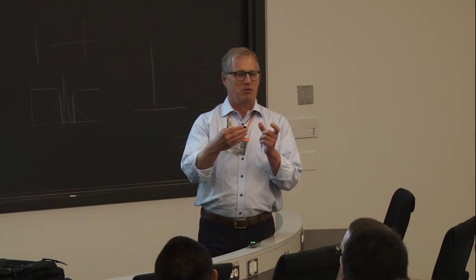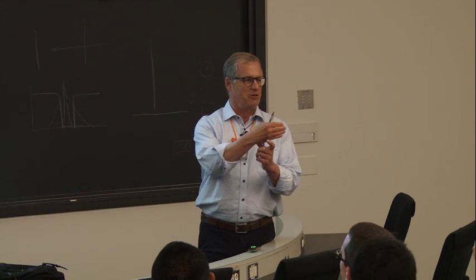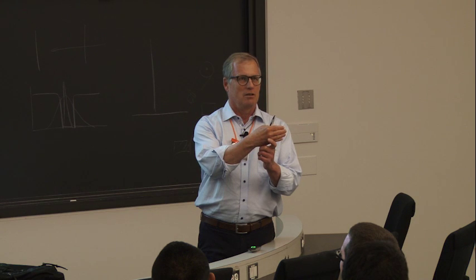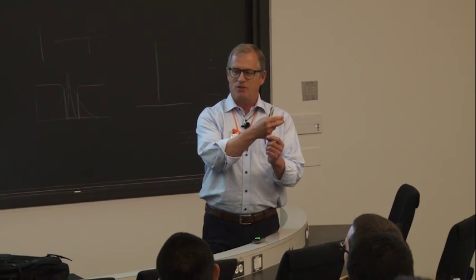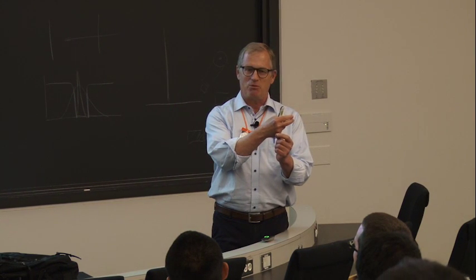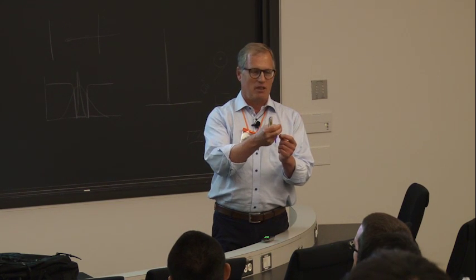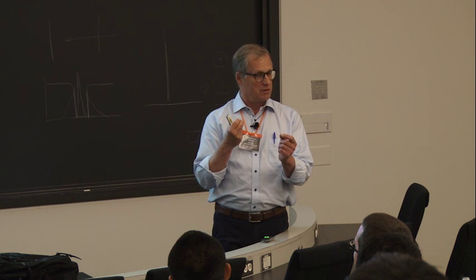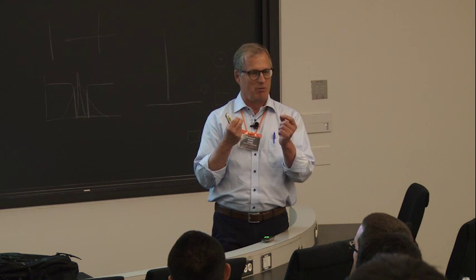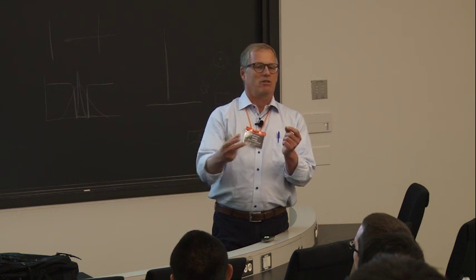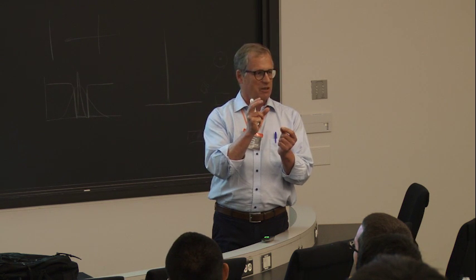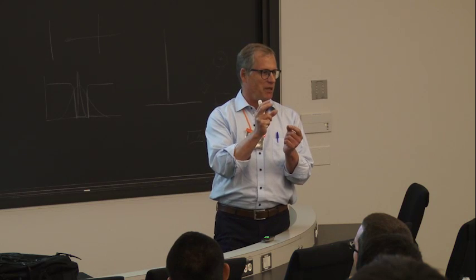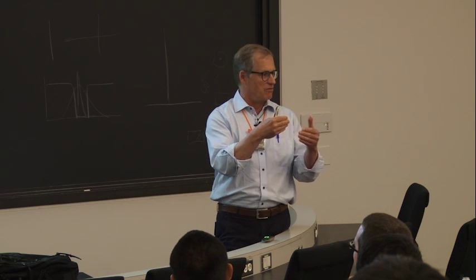Okay, if you're sampling from a deep depth of field and the laser sheet is, I'm sorry, that was the other way around. Short depth of field, thick laser sheet: stuff that's outside of the camera sample volume will actually still be seen by the camera, but out of focus. So if you use a depth of field that's too short with a thick laser sheet, you'll end up getting blur spots that are really huge. So you have to think a little bit about matching the sheet thickness and the depth of field of the camera.